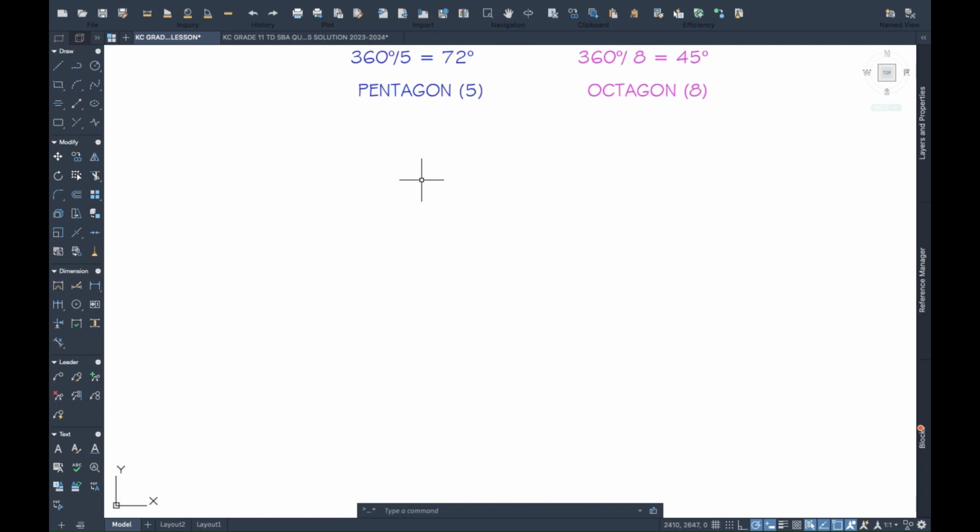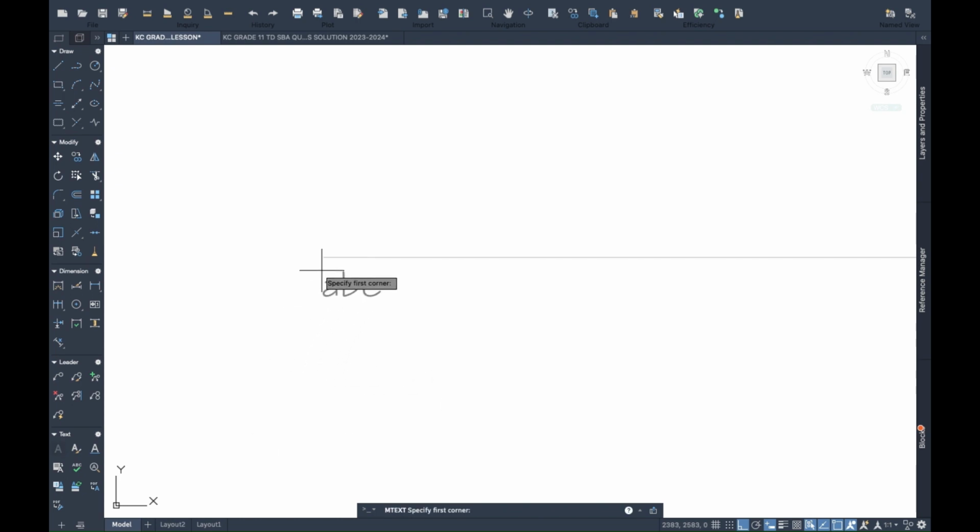Alright? So we're going to look at the pentagon first. First thing we're going to do is draw a line, and this line, turn on ortho, this line is 60 mm. Alright, so 60. And of course, with everything that we do, we want to reference the line.